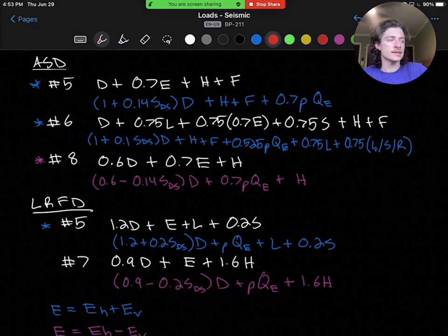Similar to wind analysis, we have defined the loading, and we would now move on to checking our design or designing the main force resisting system for these lateral loads. Moving forward, we would begin to apply this load on our structure in various combinations to elicit the maximum effect. In a multi-story structure, the force would be distributed based on portion of the seismic weight. In a rigid structure like this, each story is analyzed around its center of rigidity.